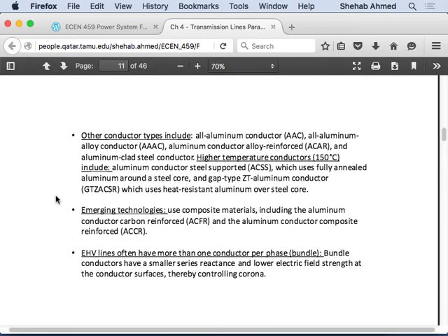Again, even though this is the workhorse of the industry, and I would say 99% of the transmission line conductors are all ACSR, many people are working on different alloys. So the idea is to give strength to the aluminum while maintaining a low resistivity, right? So people work on different alloys of aluminum so that they can minimize the amount of steel that is used by using a better strength aluminum, right? So they've come up with different kinds of conductors. I talked briefly about superconducting materials, and people are working on high temperature conductors. They're basically all alloys of aluminum, right?